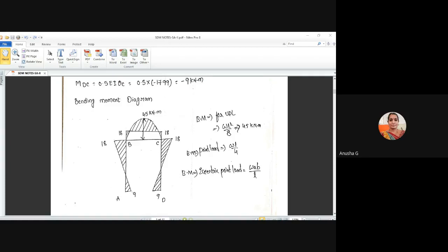If there is a load acting, depending upon the load, we'll get a rectangle or a trapezoidal form for a fixed end moment diagram. This is the fixed end moment bending moment diagram that you have to observe here clearly. For fixed end moment bending moment diagrams, mostly single bay frames they give, frames like this. Without space you have to draw like this. Practice these diagrams.